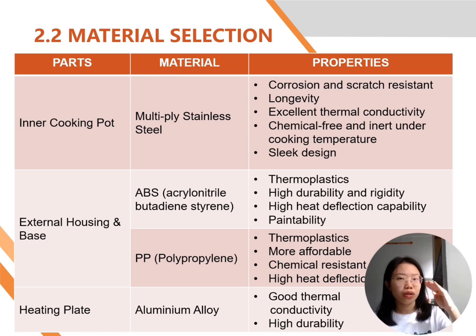So in this case, the aluminium acts as a central core, and the inner and outer layers are still stainless steel. So these two layers are stainless steel, and between them we have the aluminium central core. This modification is to improve the thermal conductivity of the plain stainless steel significantly.